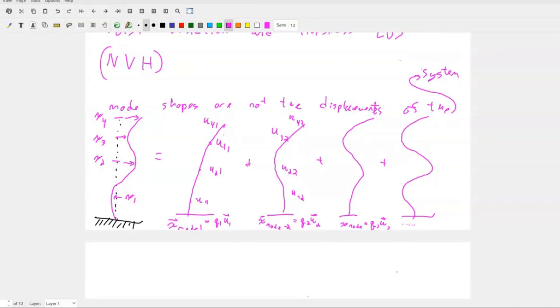The energy in a structure dies off kind of after 5 modes, right? If you want to capture the dynamics of a structure beyond mode 5, it's going to take some thinking.